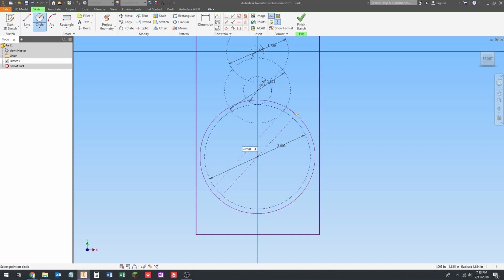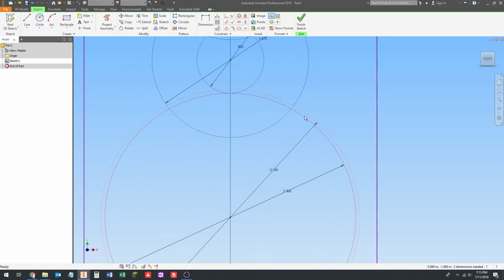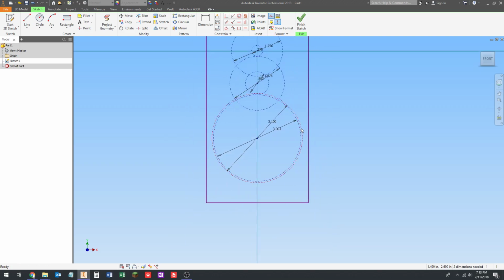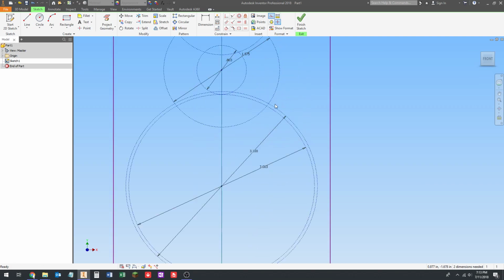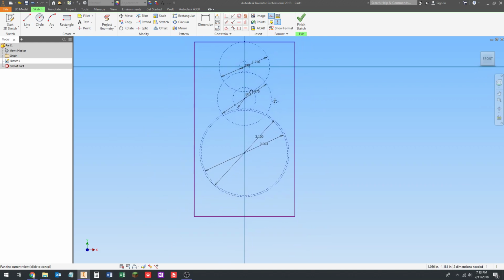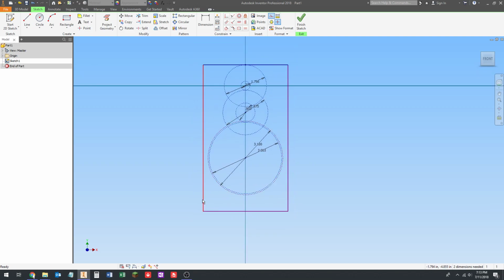Okay. Now we're not going to do the plus 3,000ths because we don't need it in this case. Then we're going to press the Enter key. You'll notice it's just slightly larger than the pitch diameter, which is exactly right. Okay, so now this represents the outside of the teeth. There's nothing sticking out outside of this, so we can be pretty confident that this is out of the way, so to speak.